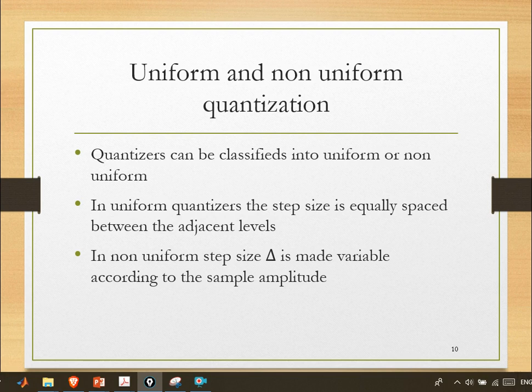Also, if you are talking with a very low voice, then the delta might be larger than the changes of your low tone, and it might not capture the details of your voice. That's why we need to make our quantizer sometimes non-uniform. Non-uniform is just like adaptive, it changes the delta according to the changes of the signal.